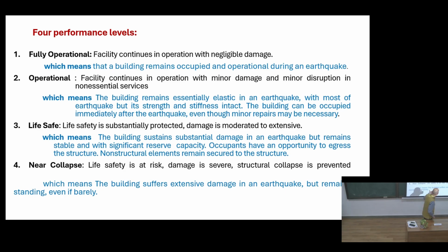So even if you go to the last level, it is not going to collapse immediately. You give sufficient warning time. Meantime, you can evacuate the people. You can save important things, precision things, machines or any other things. So sufficient warning time is there even at the last level. So in all of the levels which you are going to consider, in none of the levels is the structure going to collapse. So that is how you have to measure the performance in design. That is how you do it.